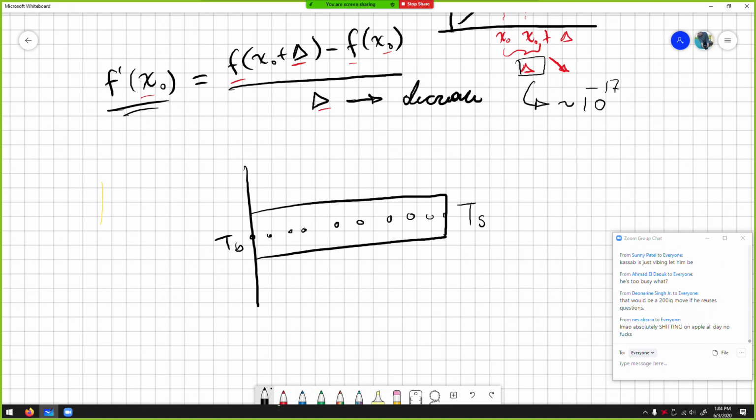So we can pack more nodes on a given geometry if we make our delta smaller. Delta represents the distance between each of these nodes. If this delta is small, I can pack more nodes. If this distance is big, the distance between each of the nodes is going to be big, and therefore I have to pack a smaller number of nodes.